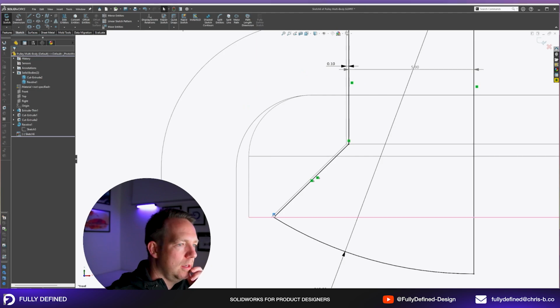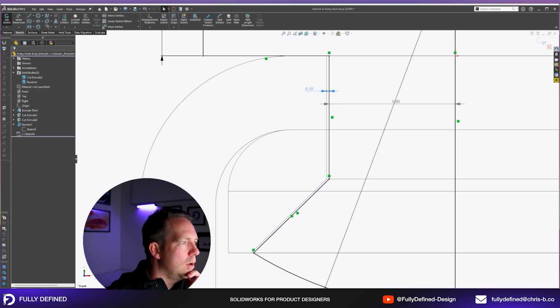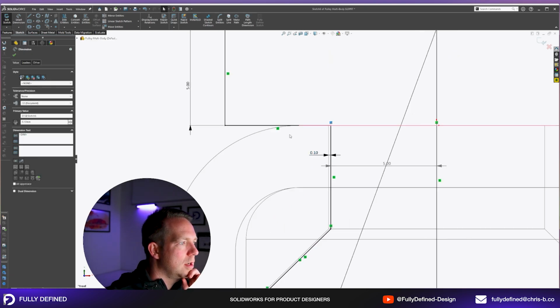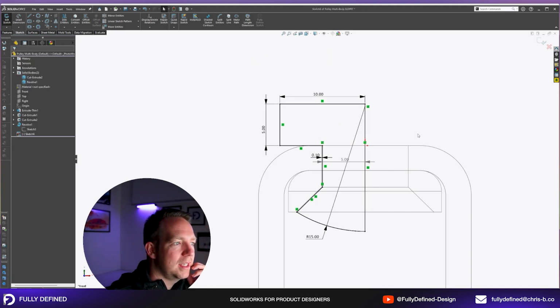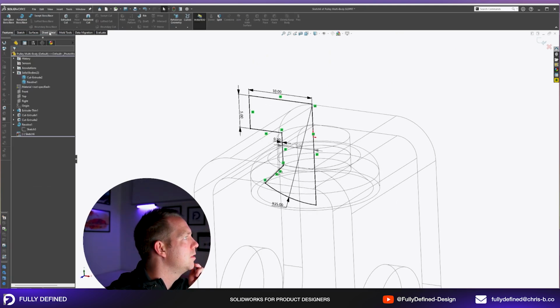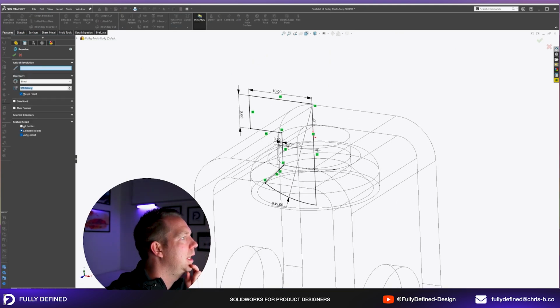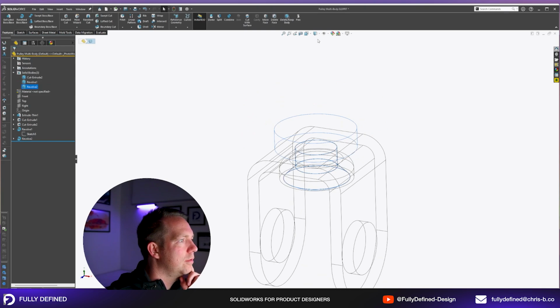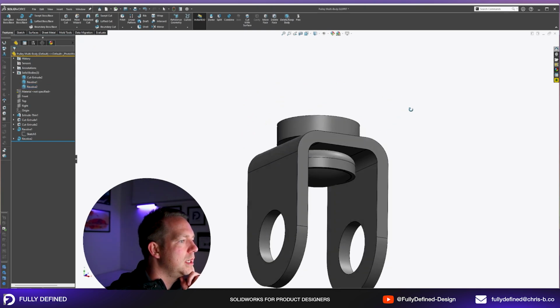Okay, so this coincident relation with the bottom of the washer, this parallel edge with the inside of the washer, this 0.1 distance from the edge of that hole, this coincident relation with the top of the form bracket, all referencing existing bodies. Okay, features, revolve, and revolving around that middle line, again, uncheck merge result. Okay, you can see now I've got 3 solid bodies here.